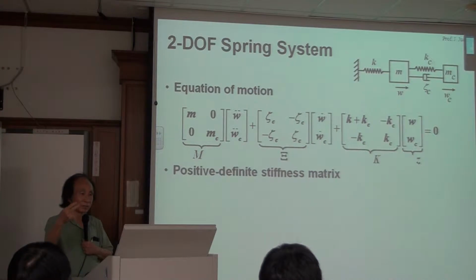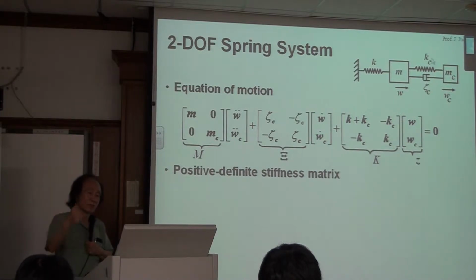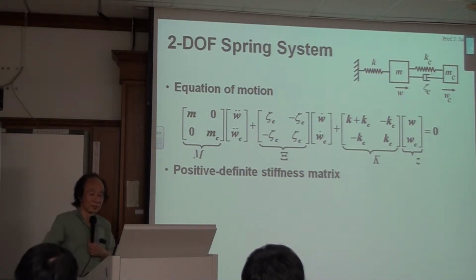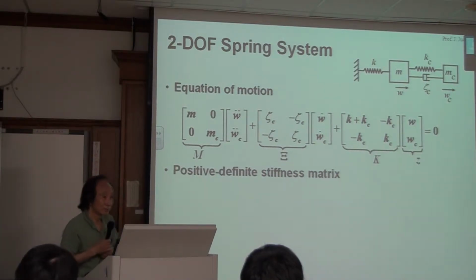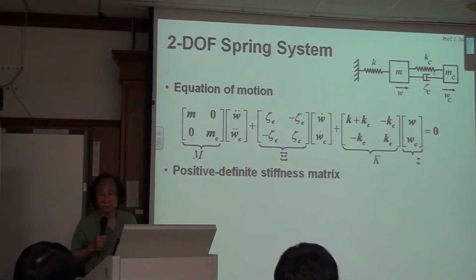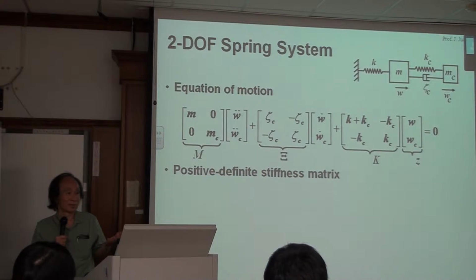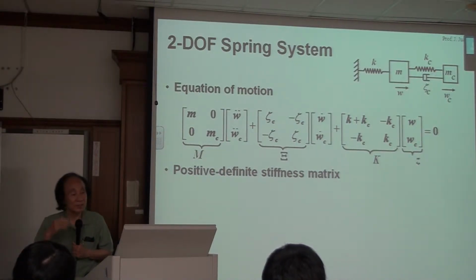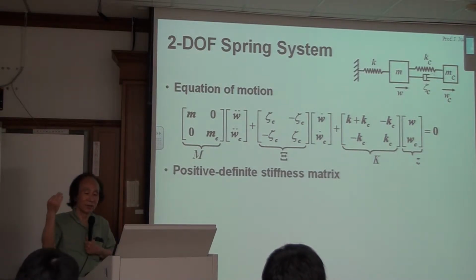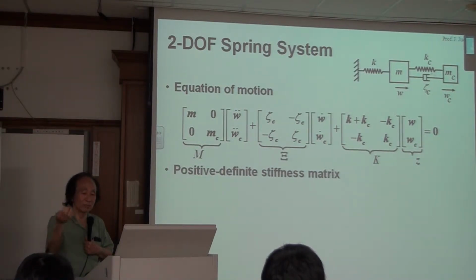Assume I have two different sensors. One is a displacement sensor. One is a velocity sensor. And I give them feedback. If I do that, then for this case, this is like a TMD, right? So the KC, ZLC, MC is a TMD. But this is an active TMD. So this is not like a passive TMD, and this requires power. We need computer power, we need sensor power, we need actuator power. So we also need a sensor, we need an actuator.